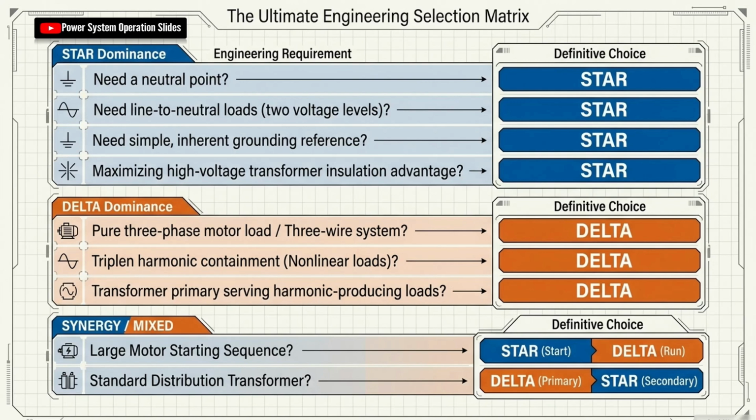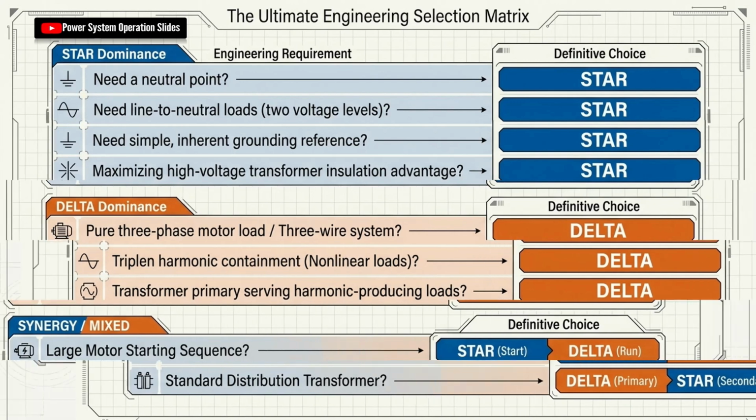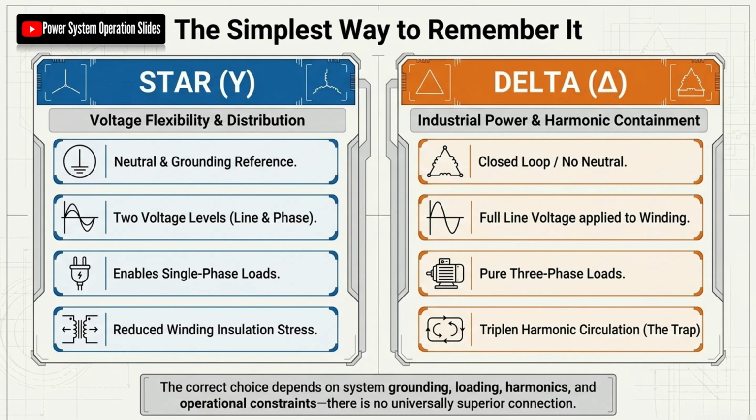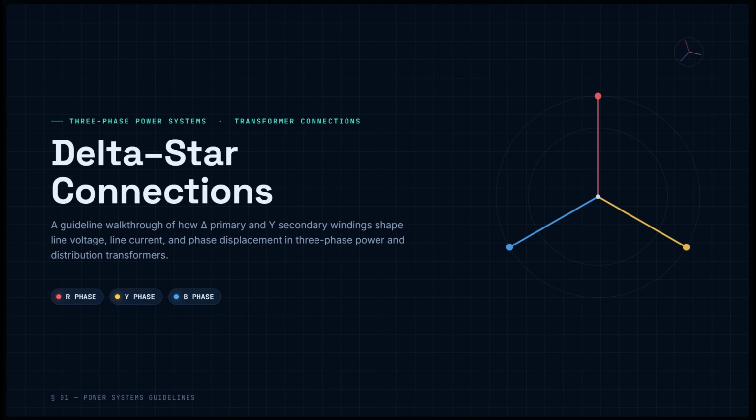These considerations become increasingly important as modern power systems incorporate variable frequency drives, renewable energy converters, battery systems, electric vehicle chargers, data centers, and other power electronic equipment. Such equipment can introduce harmonic currents, unusual load characteristics, electromagnetic interference, and other power quality challenges that must be considered during system design and operation.